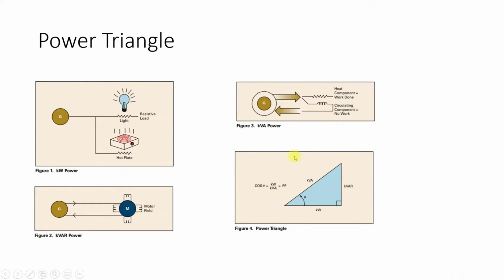So how do we represent this power? We use the term apparent power, or kVA. That's why you have seen that these motors, generators and transformers all have their power rated in MVA or kVA, basically apparent power. It's not in megawatts. The reason is that each of this equipment has some inductive load associated with it, so when the power flows through them,